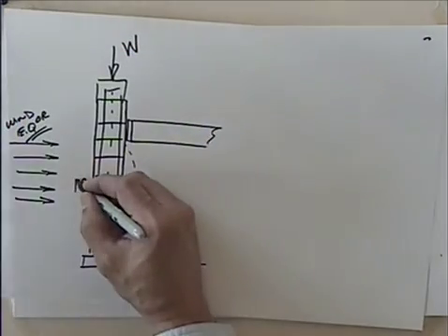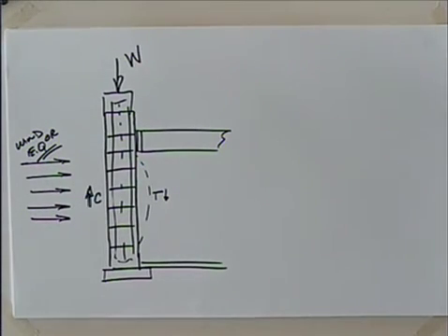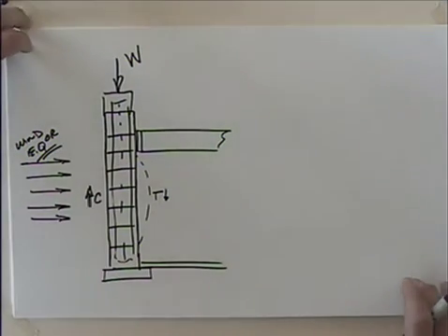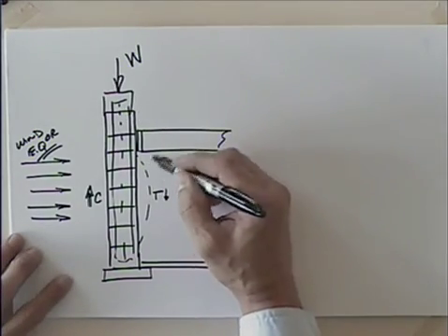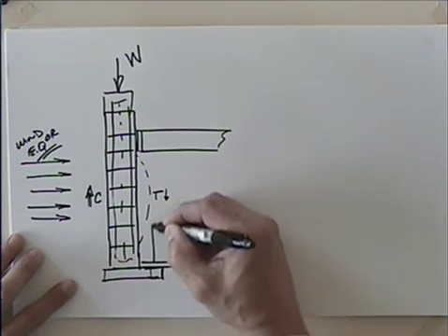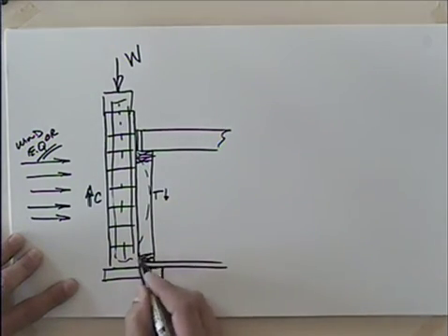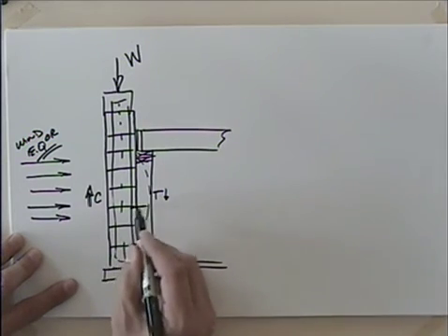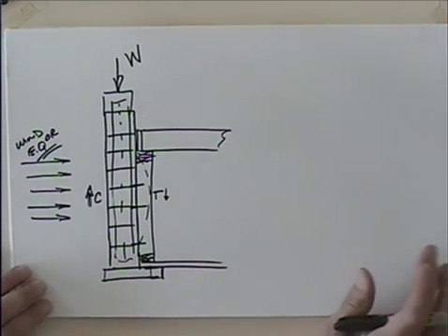Now the compression is going to go way up, okay? But you'll be able to reduce the tension maybe to something that you can manage. Maybe you won't be able to manage it, but maybe you can. That's one strategy: you grout those full. If you can put some rebar in there, all the better. We don't want to turn this into a structural retrofitting class, but if that doesn't work for you, what you may end up doing is increasing the size of this footing here, and then you come in and frame a wood or a steel wall in here, and then you attach the masonry to that wall. So basically you turn what's been your structural masonry into a masonry veneer, and you have the wall supporting that.